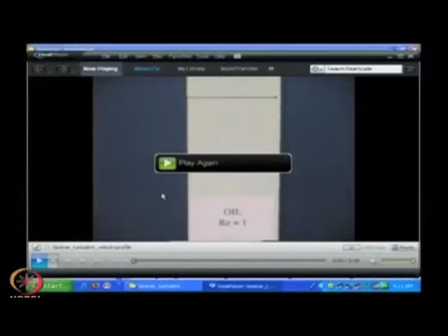You see that with a low Reynolds number there is a lot of so-called dispersion in the velocity profile. So the center line velocity is very large, wall velocity of course is 0 by the no slip boundary condition, and it is a parabolic sort of velocity profile that we have seen, like a fully developed flow through a pipe. So whatever fully developed flow we have analyzed analytically in a very nice way, that is a fully developed laminar flow. Now you look into the experiments with a high Reynolds number.